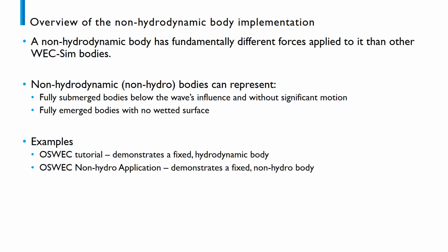A non-hydrodynamic, or non-hydro, body has different forces applied to it than other WEC-Sim bodies. The wave excitation, radiation damping, added mass, hydrostatic restoring, Morison element, viscous drag, and linear damping forces are not applied to a non-hydro body. Only gravity and buoyancy forces are applied to a non-hydro body. The mass and inertia of the body will still impact the multibody dynamics.